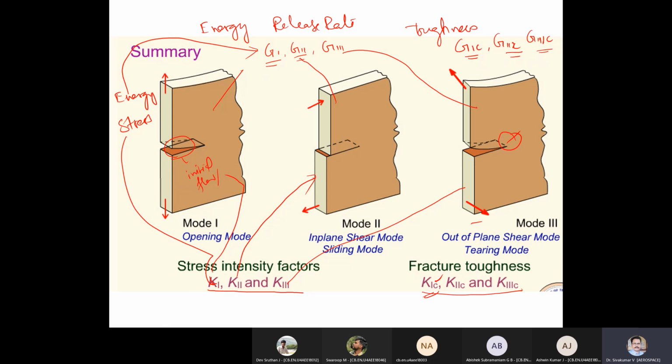With that only we are analyzing, because when the material is being made, it has some crack. So our analysis starts from there being a crack. There is no material without any crack. With the discontinuity, or the crack, or the flaw, we are estimating how much I can utilize that particular material, component, or object.